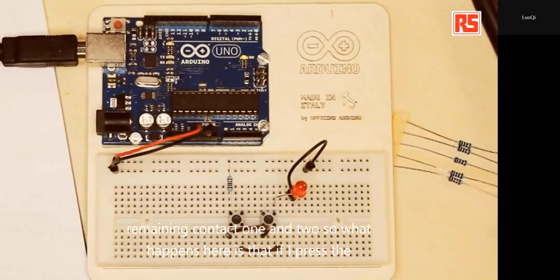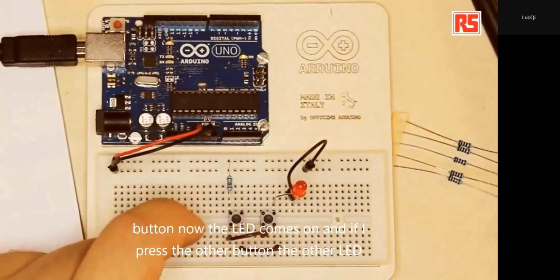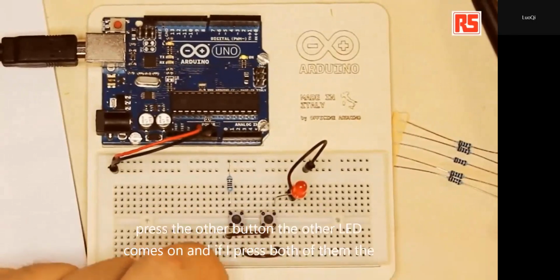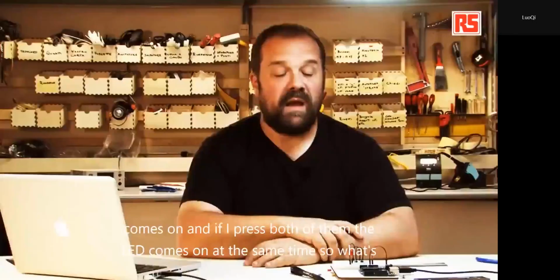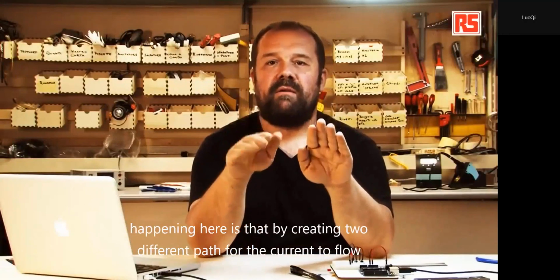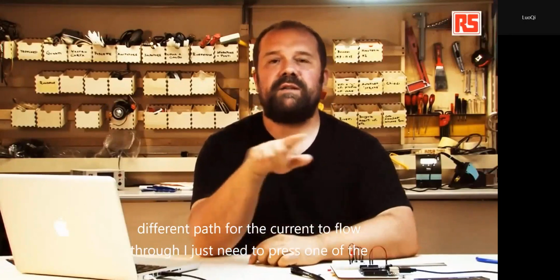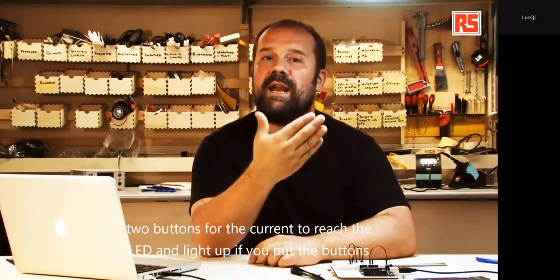So what happens here is that if I press the button, now the LED comes on. And if I press the other button, the other LED comes on. And if I press both of them, the LED comes on at the same time. So what's happening here is that by creating two different paths for the current to flow through, I just need to press one of the two buttons for the current to reach the LED and light up.